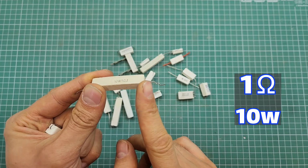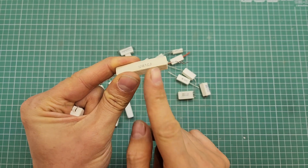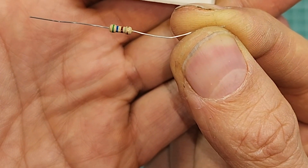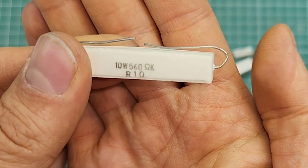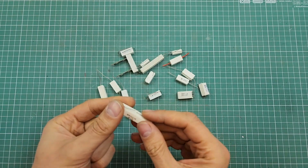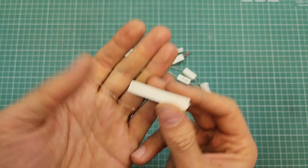If we do some calculations using Ohm's law formula and power equation, we can figure out the maximum voltage or current that this resistor can handle. For instance, take a look. This is a regular 560 ohm resistor with a quarter watt power rating, and this one is a ceramic cement 560 ohm resistor with a 10 watt power rating. Now, I'm going to use Ohm's law formula and the power equation to calculate the maximum voltage or current each one can handle.